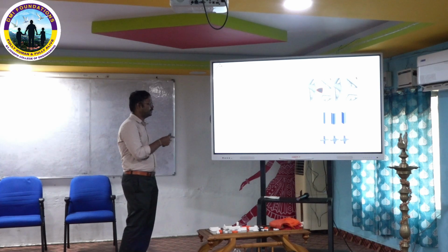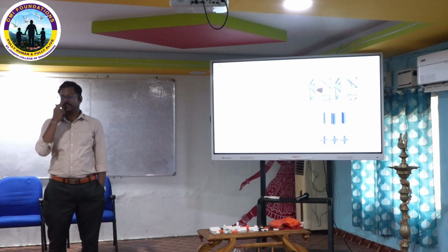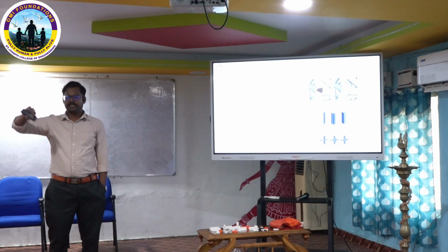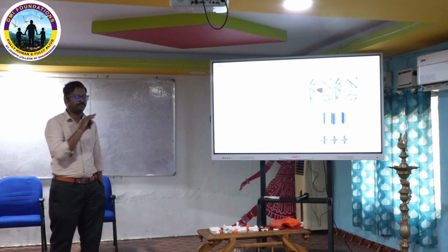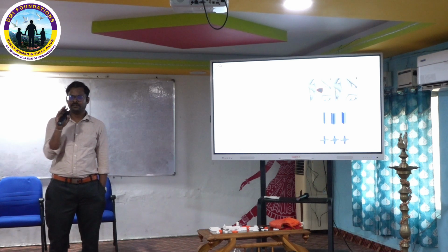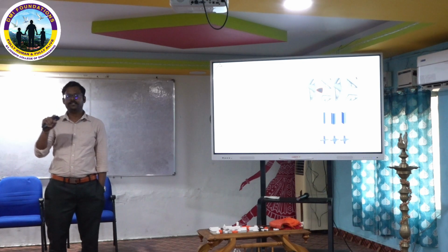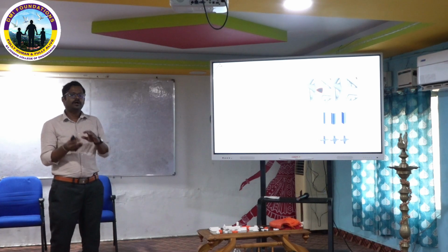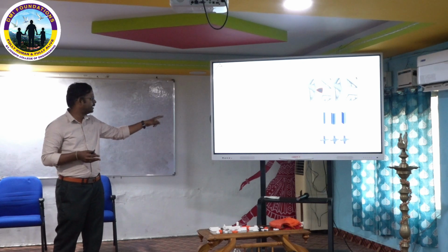Then non-linear material properties. This is a behavior we can get with the compression test. I already showed you: elastic region, then plastic region and densification region. These 3 regions we get with the compression of a lattice structure. All of that is non-linear; only the elastic region is linear deformation. The other regions are non-linear. So to get an appropriate result, you need to select non-linear behavior in your software also. Then only you can get it.